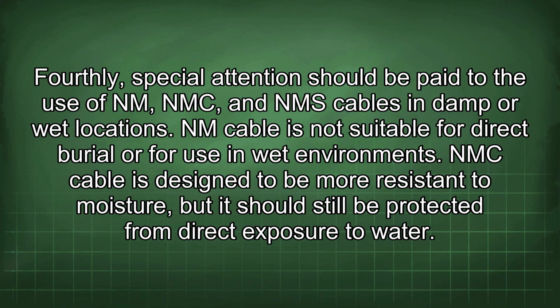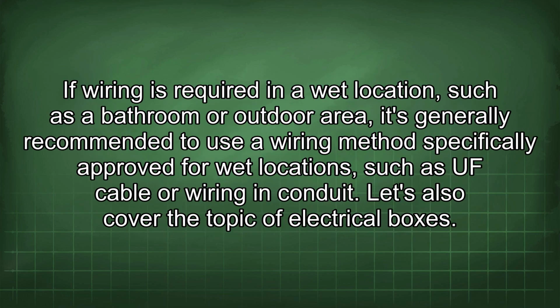Fourthly, special attention should be paid to the use of NM, NMC, and NMS cables in damp or wet locations. NM cable is not suitable for direct burial or for use in wet environments. NMC cable is designed to be more resistant to moisture, but it should still be protected from direct exposure to water. If wiring is required in a wet location such as a bathroom or outdoor area, it's generally recommended to use a wiring method specifically approved for wet locations such as UF cable or wiring in conduit.